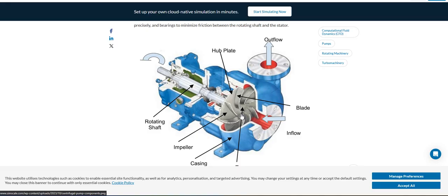So, for example, for the car water pump, I'm going to search for that. Usually you don't use a plate made of aluminium, but there are plates made of iron or steel, and this only requires folding the sides to create the shape of the plate. This can also be made by the casting process, die casting or sand casting.